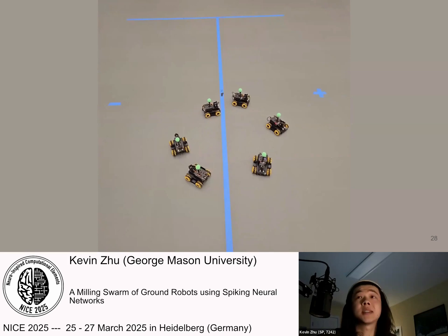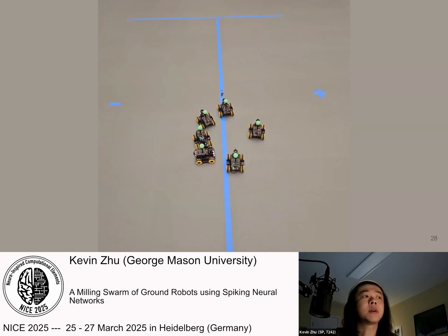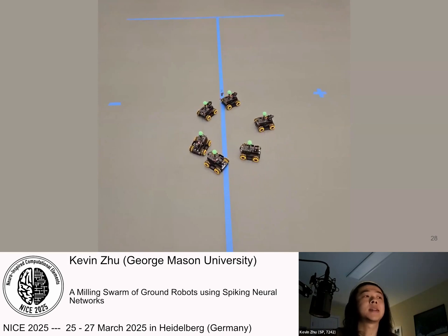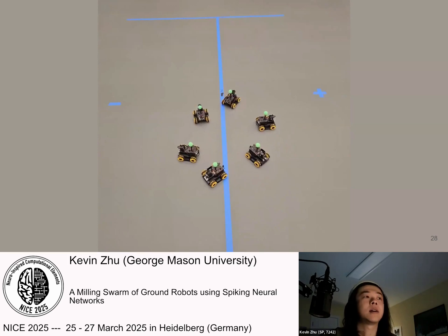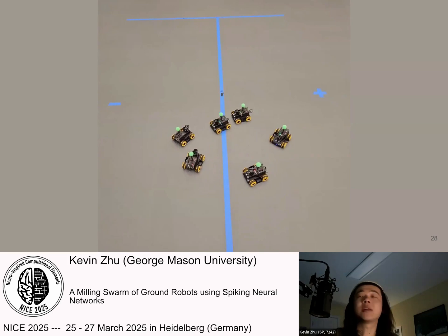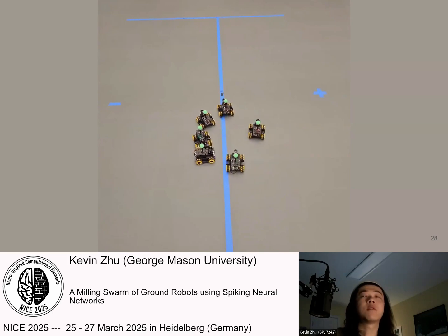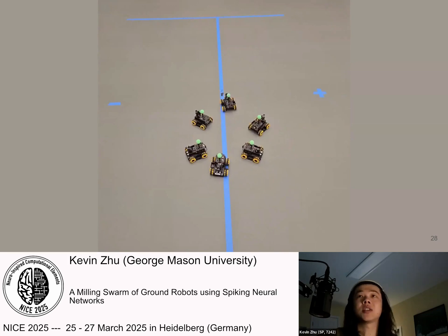And our hypothesis for why this is that there is some amount of static friction within the gearbox, because if we manually test transitioning from 0 wheel speed to some very low wheel speed, then the wheels don't turn. But if we go from a higher speed to a lower speed, then the wheels will remain turning just at the lower speed that we requested, matching our model.